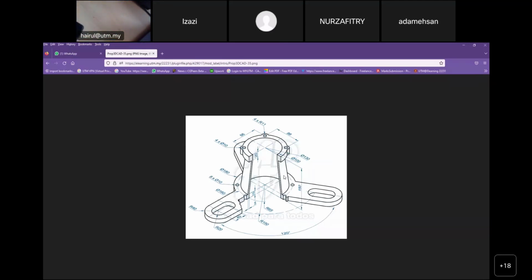Okay, so we draw the profile. What is the profile? You have to be careful. It means we have to properly sketch the dimensions. If you look at my live video again, the profile we want to revolve, you need to draw the top part. This is a straight edge, then we have a thickness here, and this is parallel, a thin wall, like that. Then we have this dimension. This one is also straight like this. Okay, this is our center line.